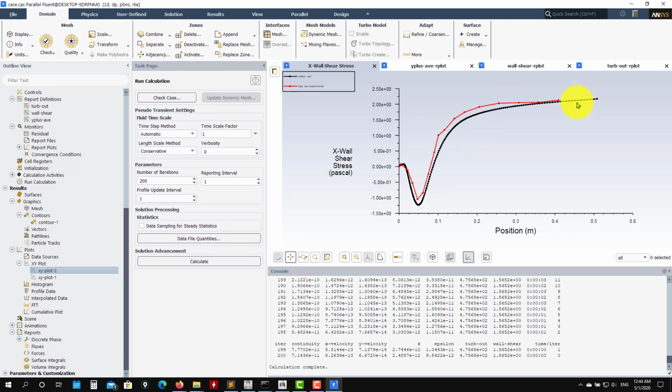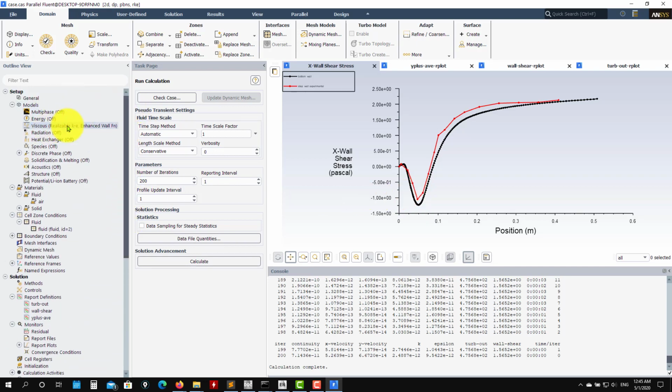Here, clearly, we see the influence of the boundary conditions. Better boundary conditions will give you a much better agreement. And you can play around also with initial conditions, get crazy values, okay? And you will see that it might converge to something different, or it will diverge, or it will converge to this one as well, but it will take much longer iterations, much longer times.